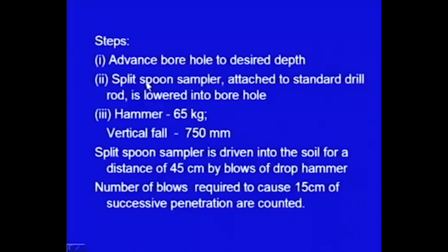These are the steps involved in the SPT. The first step is to advance the borehole to the desired depth. As I told you, we can select the interval depending on the field requirement. We can conduct at 0.75 interval or 1.5 interval, whatever is the requirement in the field.